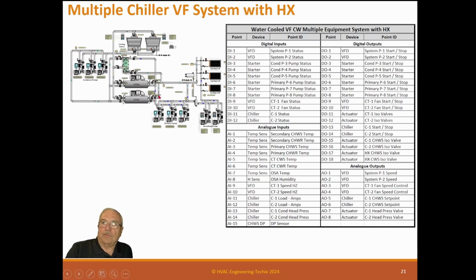So what happens here is we have a heat exchanger. And when we want to bring a heat exchanger on, we close the isolation valves of the chiller. We leave the tower on, and the tower is running water through this. And our set point now is maintained by the cooling tower fan. And those work really well if we have low humidity levels or high elevation, either one. This can save you a whole lot of energy by never having a chiller online.